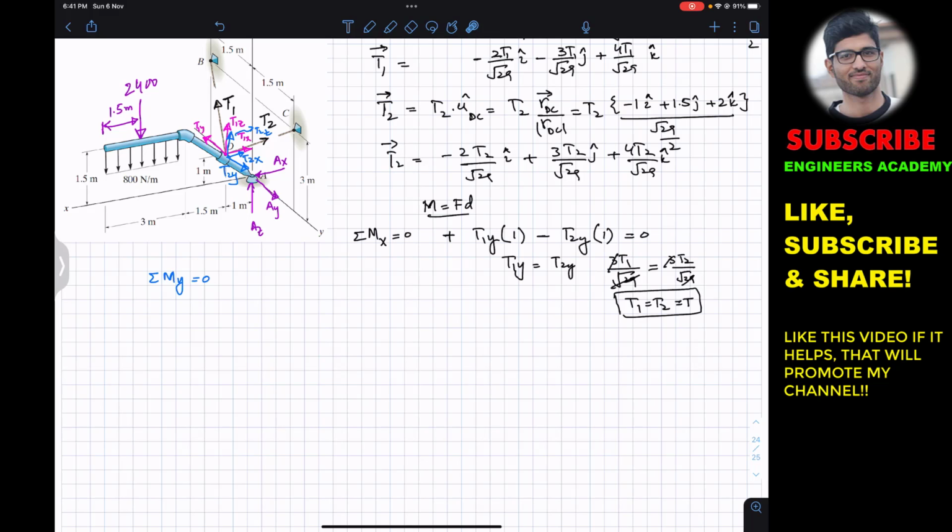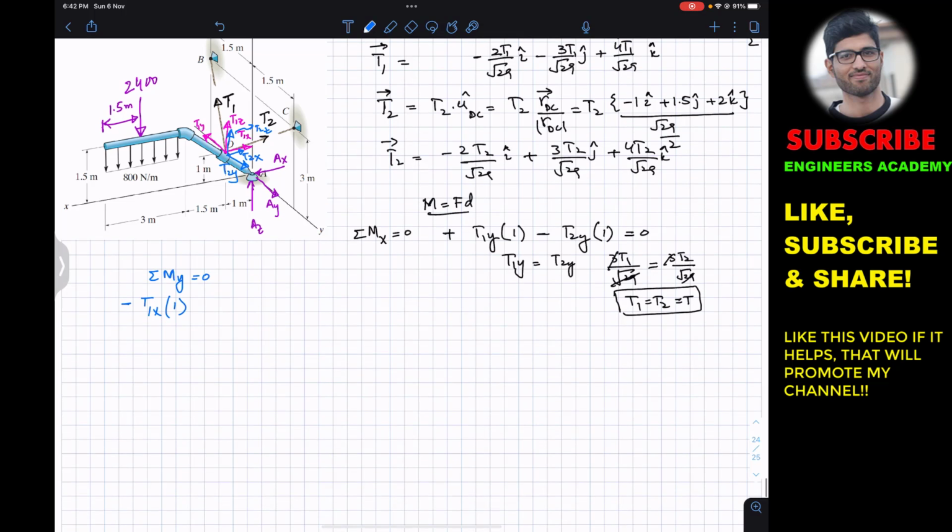Now as we can see, T2x is going to produce a moment about the y-axis in this direction. If we curl our right hand fingers in this direction, the thumb will point out in the negative y. So this means that T2x and T1x both are producing a clockwise moment about the y-axis, since we have the thumb in the negative y. So I will write minus T1x, and the perpendicular distance of T1x from the y-axis is 1 meter. That is the moment arm, so we'll multiply it by 1. Similarly, minus T2x into 1.